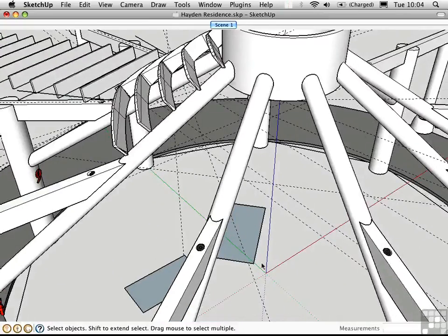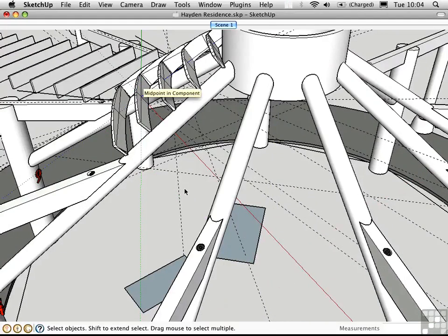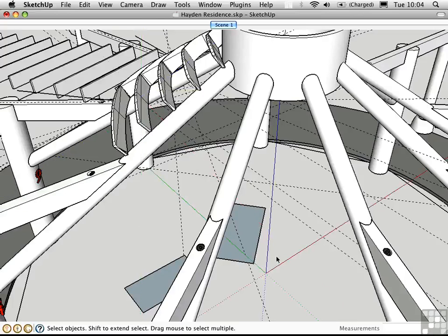So just to recap, we have Option A, which allows you to set the drawing axes. We have Control A, which toggles the display of the axes wherever they are. And we have Shift A, which resets the drawing axes. If you want to change the axes numerically, you have to right-click on an axis and choose Move to access this dialog.